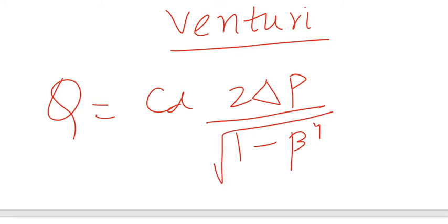So the idea is how they got the discharge coefficient CD. What is CD? C is the correction factor for friction in the pipe, friction in the Venturi, the losses because of pressure drop, pressure losses because of friction. So delta P measured in lab includes the friction as well.